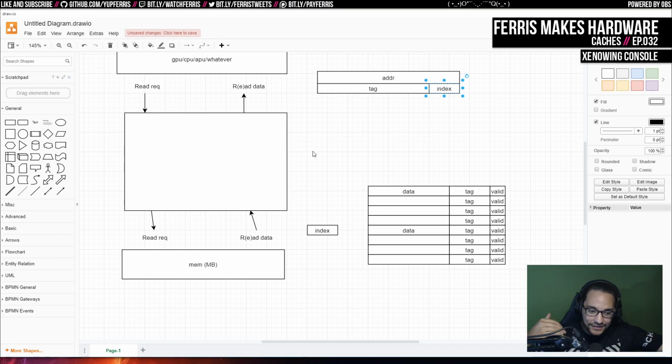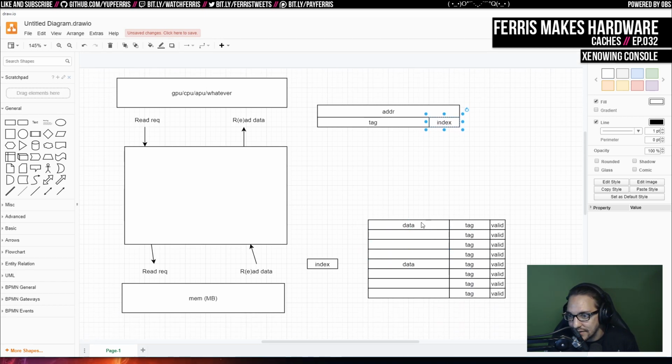I'm also illustrating what's called a direct mapped cache, though I'm not really going to talk about associativity here. But basically every 8 addresses would have the same index, and you want to differentiate the first entry in memory versus the 8th. So you need this additional tag to make sure that those are different between different requests. That way, when you have an index for 2 addresses that maps to the same line, you can accept or reject that, determining if that's actually the data that's valid. But anyway, this is basically how it works.